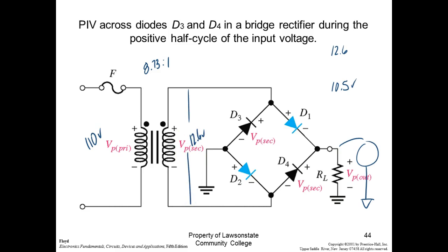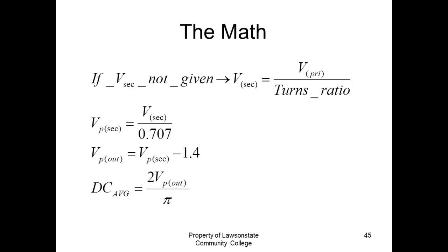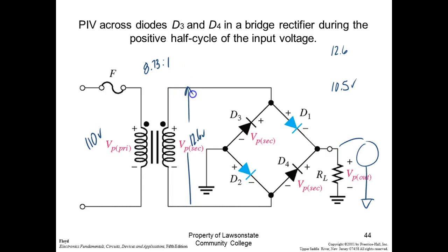So you're right, that would be 12.6 volts RMS. Not yet. No, you don't divide this by 2. This is not a center tap transformer. Y'all understand that? We divide by 2 if it's a center tap transformer. These rectifiers are across the whole thing. On the other ones, each diode was only across one half of the transformer.